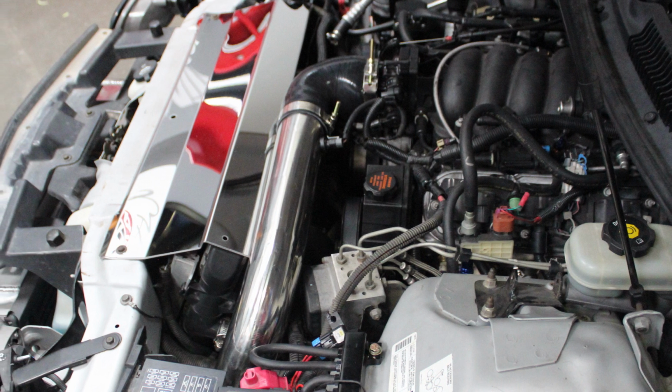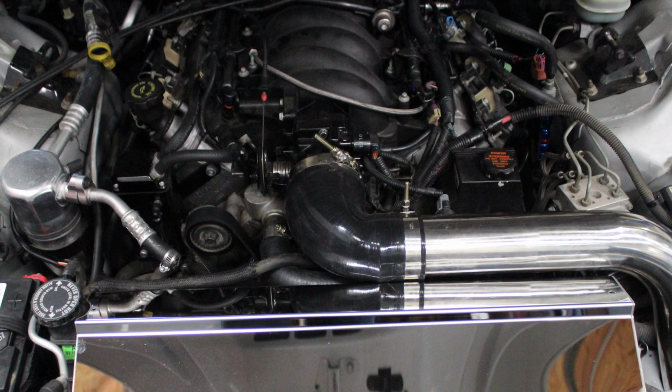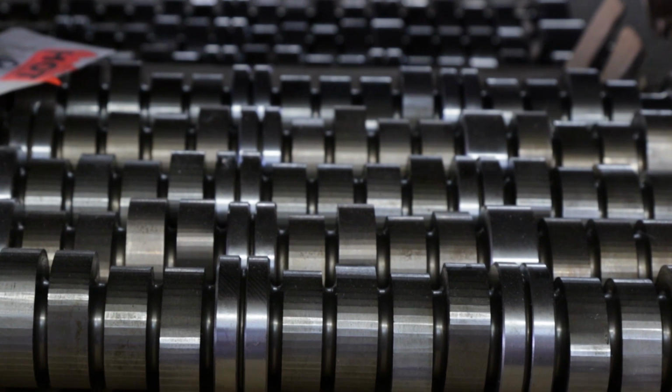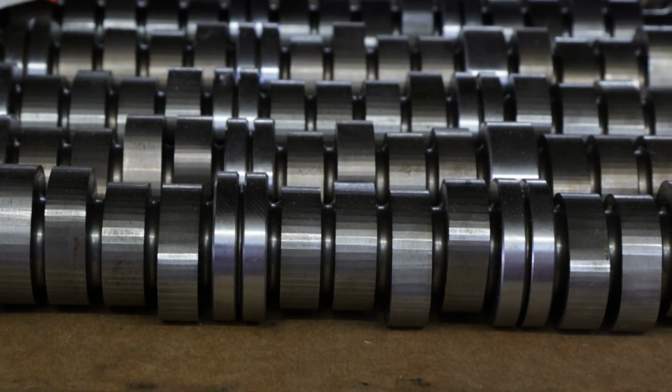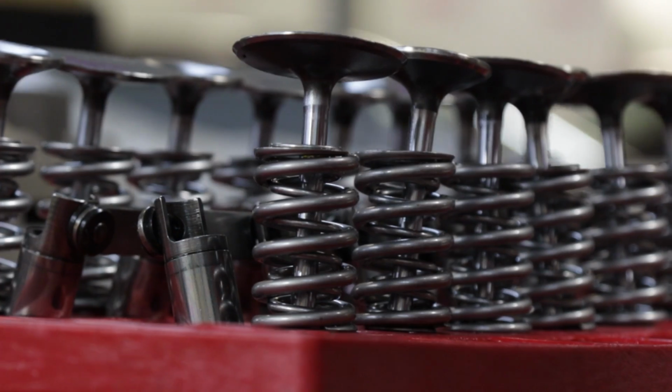Sometimes you'll see people do a turbocharged application, with high back pressure, and put an NA style camshaft in, and there'll be so much flow of burnt exhaust into the intake manifold that you'll see brown or black char in the intake manifold.